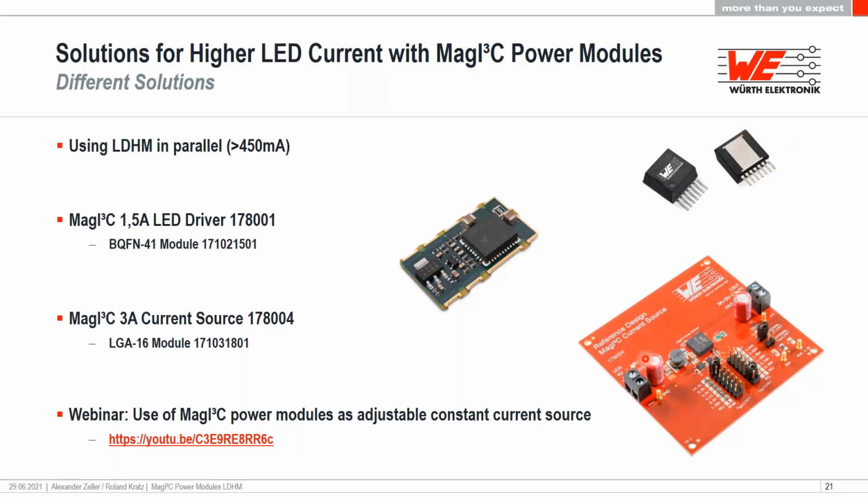With these 2 reference designs, we use a power module which is a buck regulator which has a voltage regulated output, which means the feedback resistor divider gives the output voltage back to the feedback. These modules of this PCB and this PCB are used initially for generating a constant output voltage.